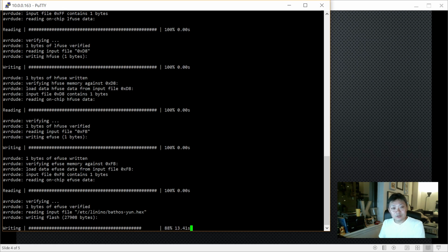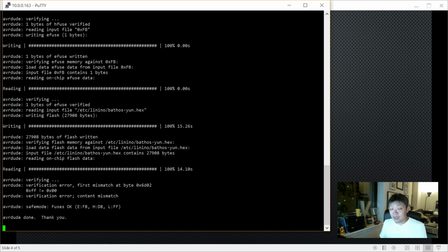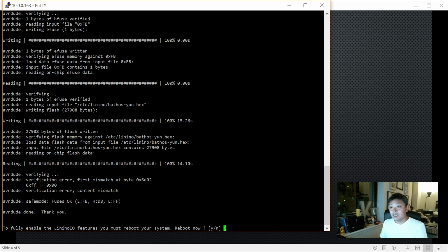Now, once this script is run, you can create the AllJoyn JavaScript scripts that will actually access your IOs and everything else that is available on the Arduino Yun. You can still go ahead and upload a sketch to your Arduino, but if you do, it's actually going to disable the IOs from being usable in your AllJoyn scripts. So if you want to use those AllJoynJS scripts again, you're going to have to run that /usr/bin/linino-IO start again. And the final thing is rebooting.